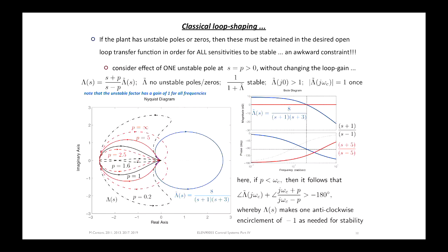Okay, so this is really suggesting that you need to have large gain, right, at frequencies that correspond to the frequency where an unstable pole will roll off. Okay, which we've seen before via the time domain integral constraints towards the end of part 3 of the notes. So it's just confirming this.